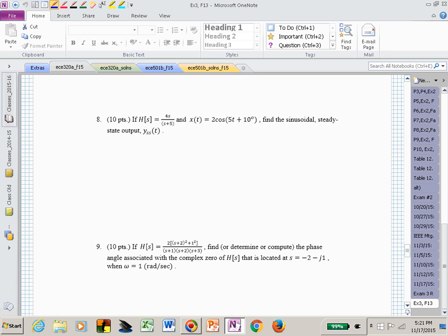But for poles, if you ask what's the angle associated with the pole, let's say at -1, you would just compute its angle. But if I said, what is the angle contributed by the pole to the transfer function at, then it would be the negative of that angle. Is that verbiage confusing enough? I'm not trying to trick you. I just want you to understand the distinction or the difference.